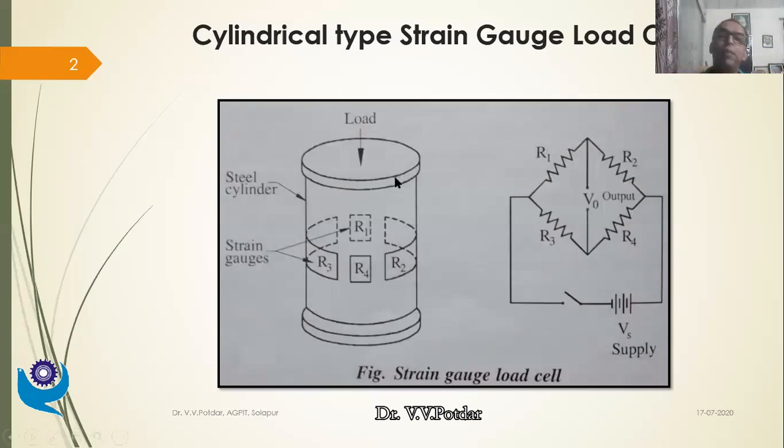So this is a cylindrical specimen. Stress upon strain is E. So E I know of this specimen material. I have just measured the output voltage and I have just got epsilon value. So stress upon strain is equal to E. So E I know, into strain I know. So I know stress in case of this cylindrical specimen. Force upon cross-sectional resisting area is stress. So force will be equal to stress into A.